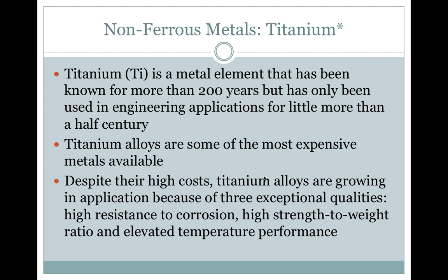Titanium. Titanium is a metal element that has been known for more than 200 years, but has only been used in engineering applications for little more than a half-century. Titanium alloys are some of the most expensive metals available. Despite their high costs, titanium alloys are growing in application because of three exceptional qualities. They have a high resistance to corrosion, a high strength to weight ratio, and elevated temperature performance.